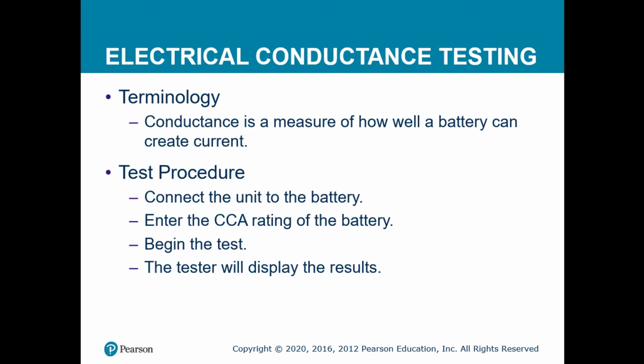This is kind of the king, conductance testing. Conductance testing is done with typically a Midtronics tester. This is pretty much the standard in all of your shops now. This is designed for warranty. So as far as whether or not you're going to cover that battery under warranty, it has to have a conductance test done on it.